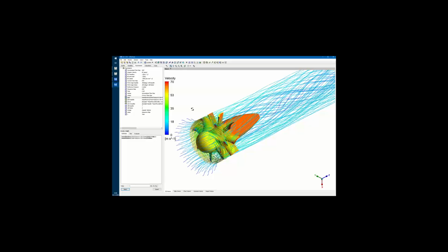Is there anything you would like to add, Sasha? No, that's all. I think that was a very good explanation. I have to admit there are no problems with small features. It all depends on the meshing tool. Small features with TurboGrid are not a problem, and small features inside of Ansys meshing depend mainly on your mesh settings and how far you are willing to refine, or how far you need to refine, in order to achieve a mesh independent result.